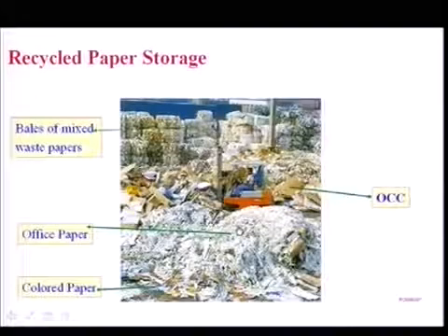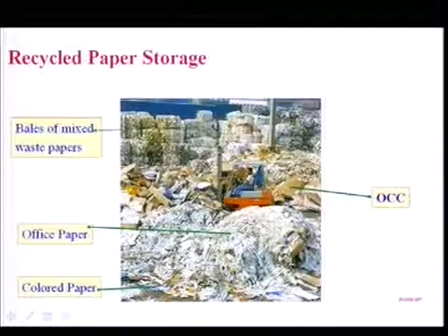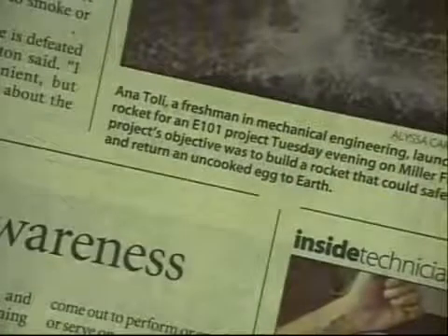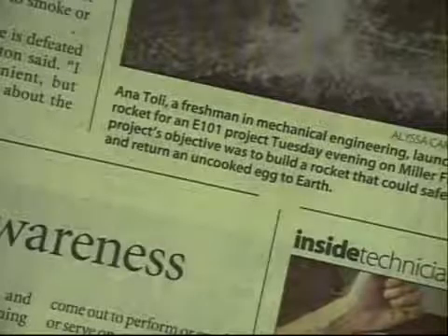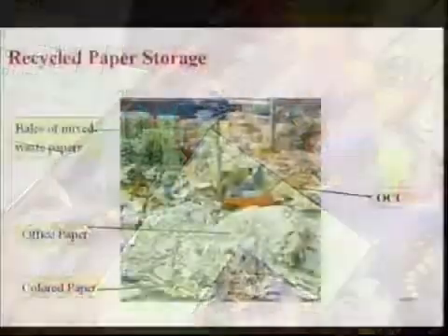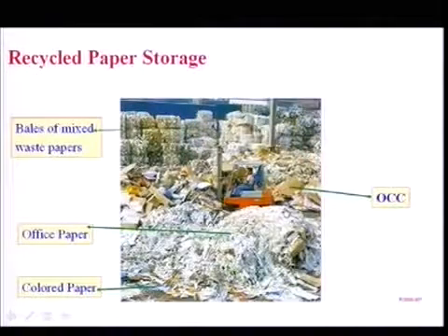And also you have OCC, old corrugated container boards, brown fibers. Then you may have some newsprint in this paper mixed in. That's a newsprint paper. This is how it looks like. 58 brightness there. And then there may be some magazines like this, with a high amount of ash and glossy shining magazines present in this paper. We need to recycle all this and we need to bleach it to make a nice bright white paper. How are we going to do it? That's what you are going to see in my presentation.